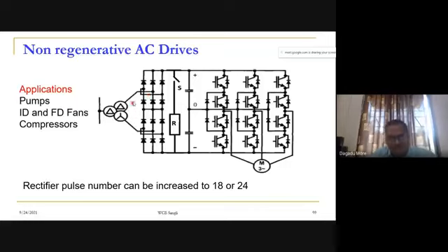And yesterday we discussed, for obtaining a 12 pulse, whatever supply we are giving to the first bridge and the supply we are giving to the second bridge, they should have a phase shift of 30 degrees. Because of that we are getting 12 pulses in the period of 2 pi. Because of the star winding and delta winding, we have seen that fifth and seventh harmonics are eliminated from the supply.